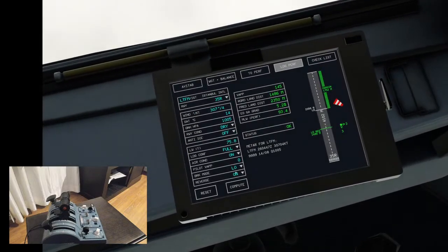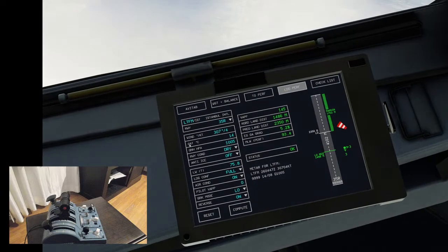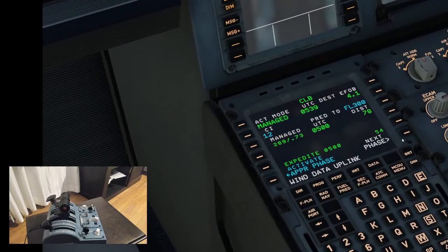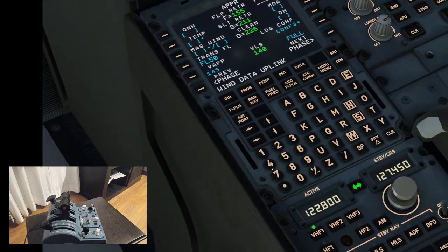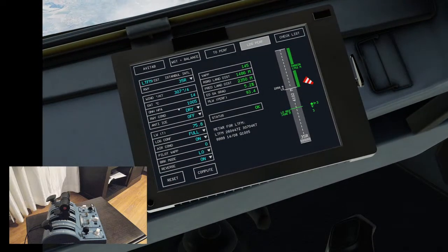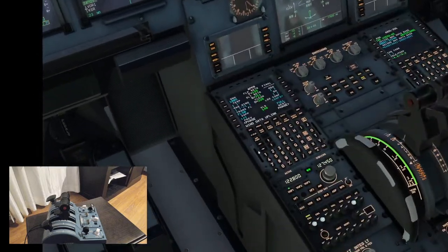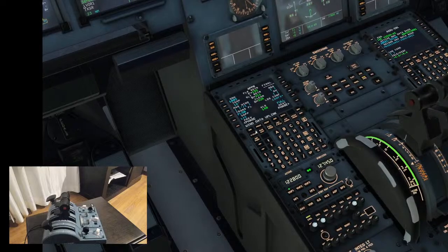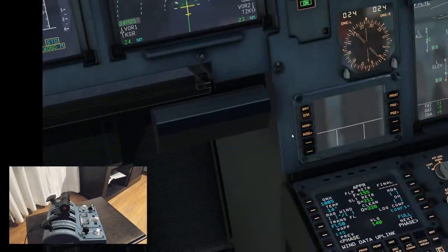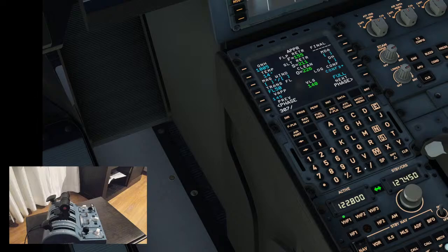And then I'm computing, by the way, reverse on, yes, landing configuration full and air conditioner off, and our landing weight will be 75 tons. And then here is the performance page. I'm setting all the configurations here. QNH, last QNH was 1005, and temperature in Istanbul will be 14 degrees Celsius. And then wind direction and speed, here is 3 at 4 knots. I'm transferring all data here.